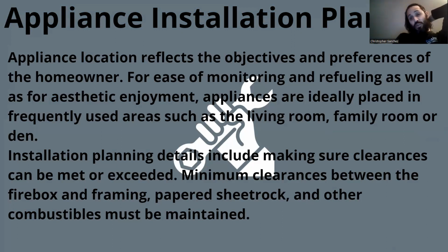So yeah, man, wherever these individuals are planning to put the fireplace, it's super important that you're understanding where they're going with it and how it relates to the clearances, to the rules of the game. A lot of times I also find too, like, how far is it going to bump out in the room, what's going to go in front of the fireplace, are they having a hearth extension that's going to go out in front, how high is it going to go. All these are really important when it comes down to your clearances and meeting the manufacturer's codes and specifications.